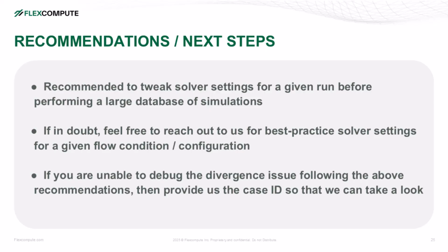This helps you achieve reliable convergence while controlling computational cost and flex credit usage. If you encounter persistent divergence in specific cases after applying these guidelines, you can share the case ID with the support or application team so they can investigate further.